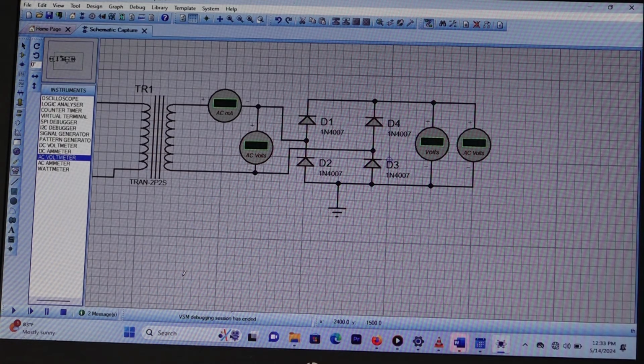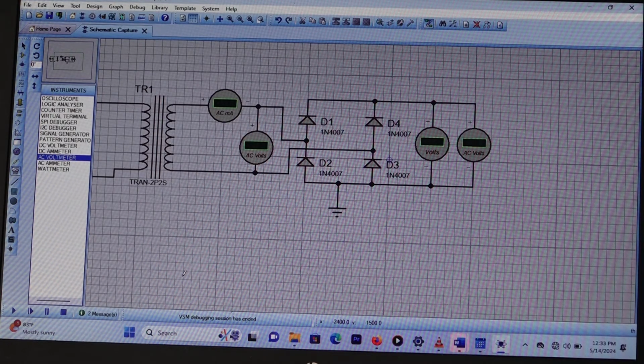We discussed the filter. I talked about capacitive reactance in the previous session and how we can calculate it. We realized that an electrolytic capacitor provides a small amount of capacitive reactance against AC power, but infinite resistance against DC power. So when we introduce the capacitor and connect it in parallel with the bridge rectifier, we are going to have two networks. One network will be towards the capacitor, the other towards the voltage regulator. So you see all the AC components will be drawn through the capacitor towards the ground.